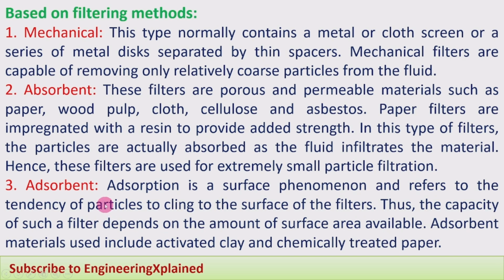The next one is adsorbent. Adsorption is a surface phenomenon and refers to the tendency of particles to cling to the surface of the filter. The particles present in the working fluid will be attached to the surface and thereby separated from the working fluid, and that is called adsorption.